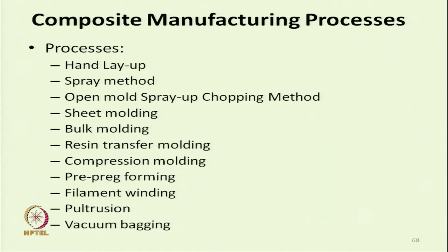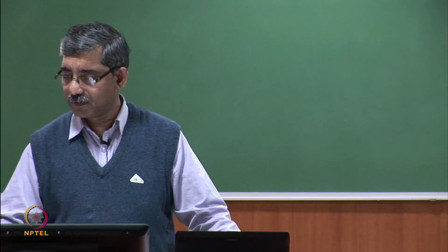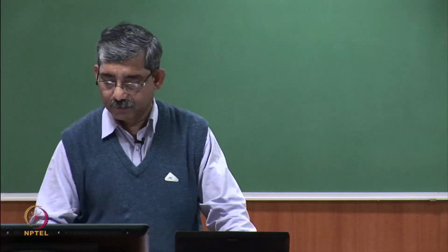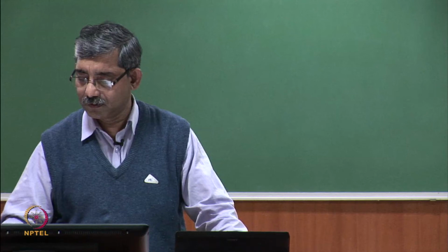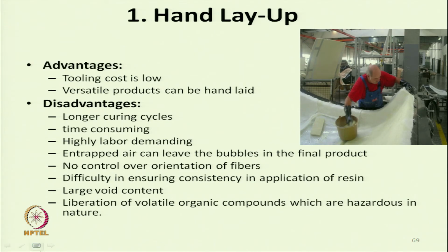As the name implies, hand layup means manually we have to mix the matrix with the reinforcing material. Here we can see the person is laying up the thermoset matrix, which is with a low viscosity.